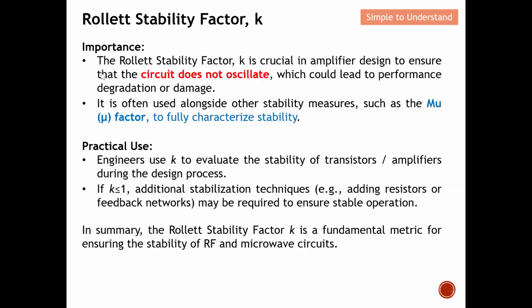Why do we need to study this Rollett stability factor? It is very crucial when we design an amplifier. When we design an amplifier, we need to ensure that the circuit does not oscillate. Why? Because once it oscillates, we may have potential performance degradation or even damage to the amplifier design.